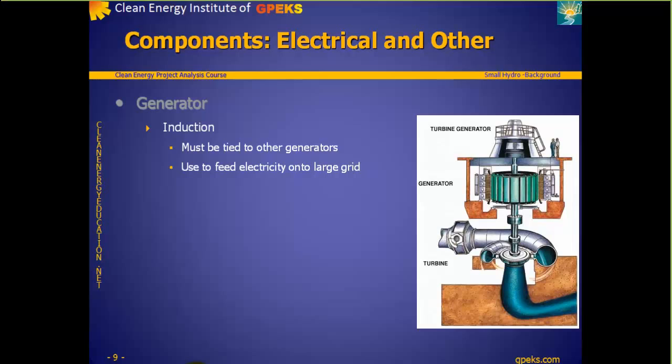Note that there must be alternating current already present at the electromagnets for the induction generator to operate. While it is possible to use auxiliary circuitry or generation equipment to furnish this current, this type of generator is normally used only when it is connected to the central grid, or a grid containing synchronous generators.